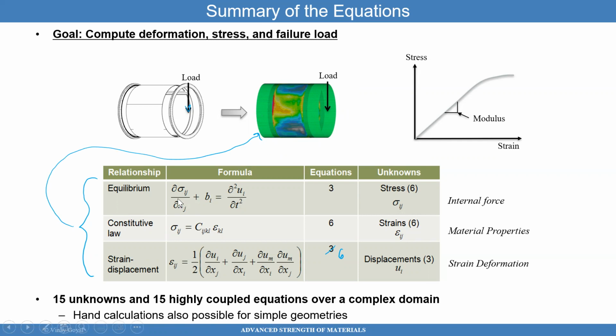And guess what? Now I have the equilibrium equations, I have the constitutive law, I have the strain deflection relationship. I can plug the strain into this equation, the stress into that equation. Now everything is in terms of deflections. I have 3 equations here, 3 unknowns, which are the deflections. I can solve for the deflections. Once I know the deflections, I can get the strains. And once I know the strains, I can get the stresses. So in reality, I am ready to go here.